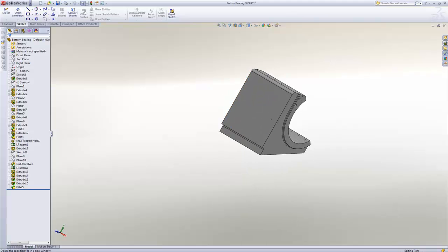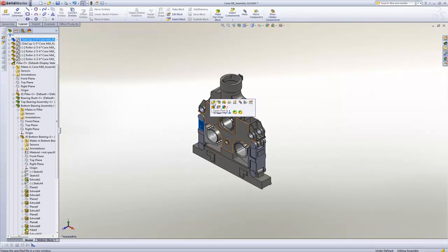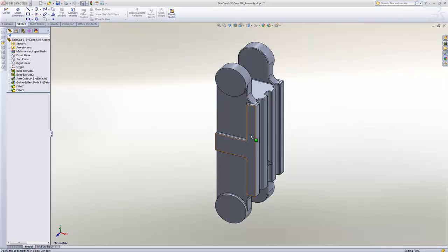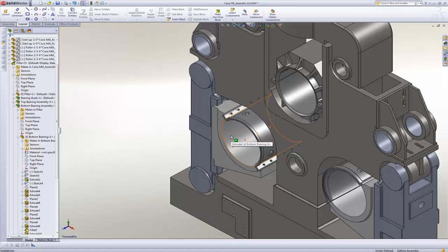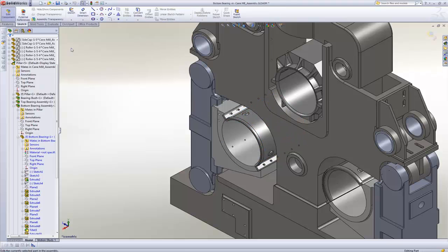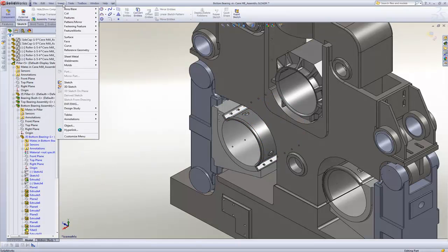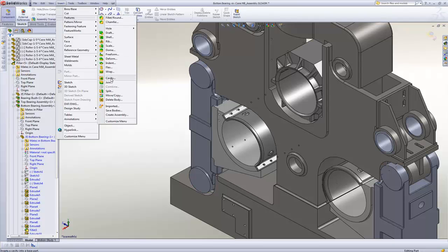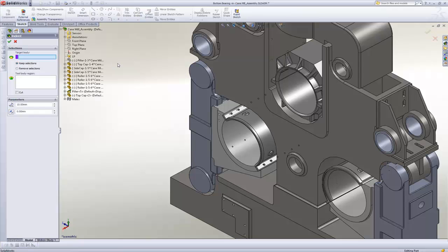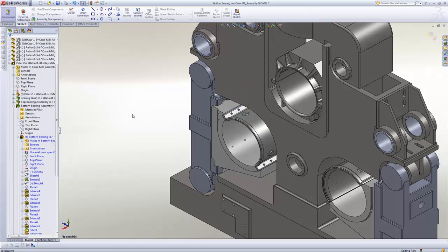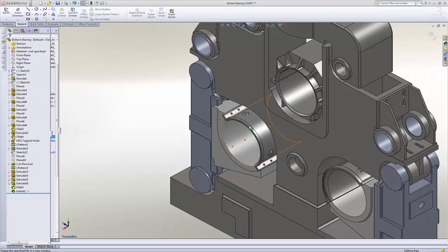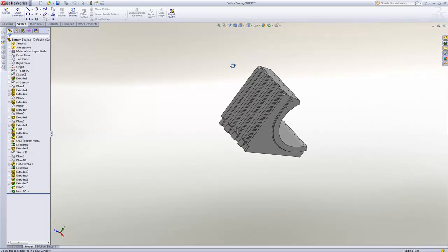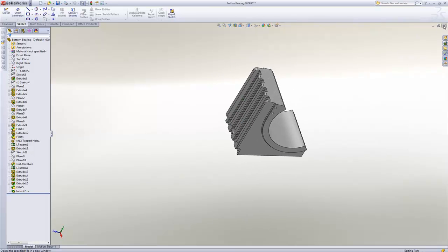I would like to draw your attention to the bottom bearing back face. There is no guide as in side cap. We can easily indent the existing guide onto the bearing back face to speed up the design process. Indent is a really powerful feature that would help us to form the existing guides from the side cap onto the back face of the bearing bottom.